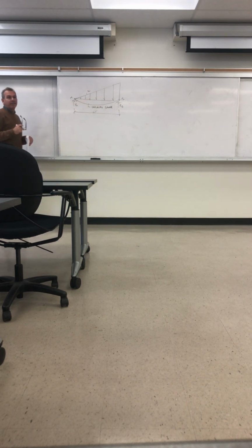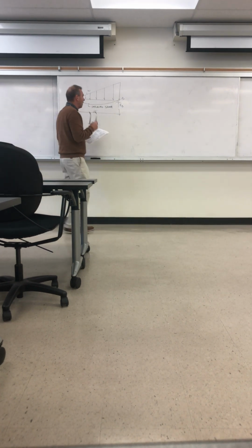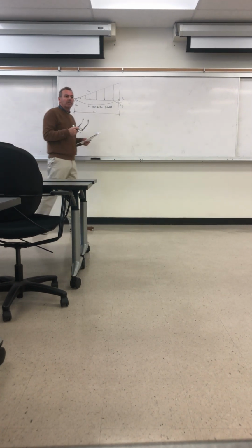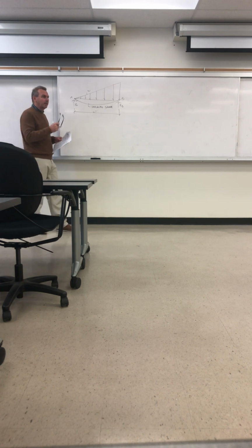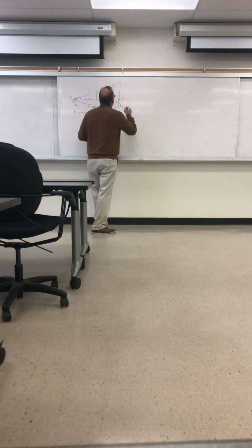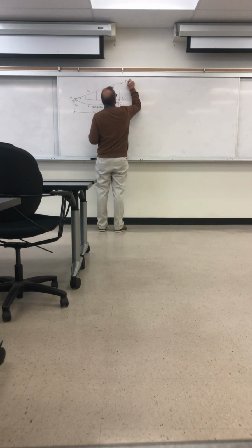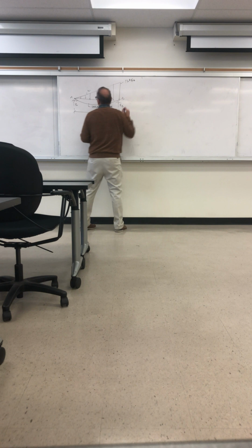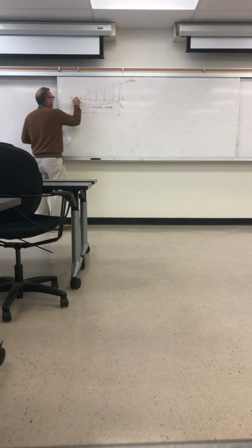Distributed load is not an evenly distributed load, it's varying along the length, as we've seen before. Here we're not just solving for the reactions, but we're also solving for the shear and moment diagrams, right? Whereas before, when we saw something similar, it was just the reactions we solved. And the intensity at the right is 13 kips per foot. At the left, you can see it's 0.